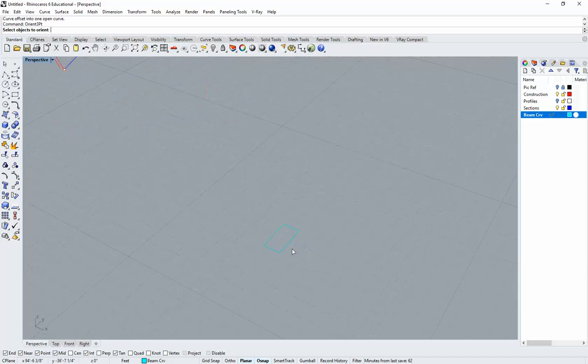This object that we want to orient is here. The reference point we're going to want to be the center. So the first one is going to be the center. In your OSNAP options down below, click on your center snap and find your center. Your second one could be the midpoint, and your reference point 3 should be one of the corners. In this case, I'm going to go to the negative x direction because that's where I made my offset.